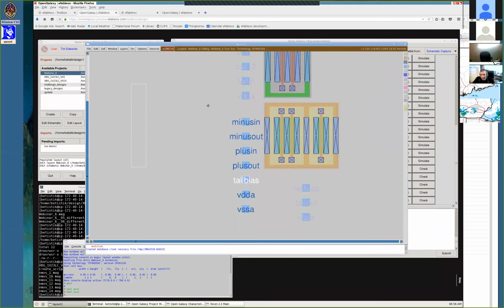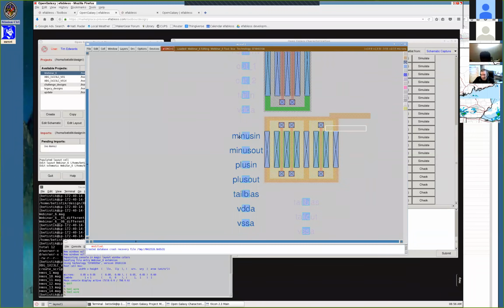And so if you want to create a well-connected substrate, you want to use subdiff here. It's not quite the same as the subdiff that exists in here, but it is, I think, compatible with it. I think that does, yeah, okay. So you can connect up using this subdiff layer. You are allowed to paint with this layer, and you can connect up to the substrate layers in other cells.